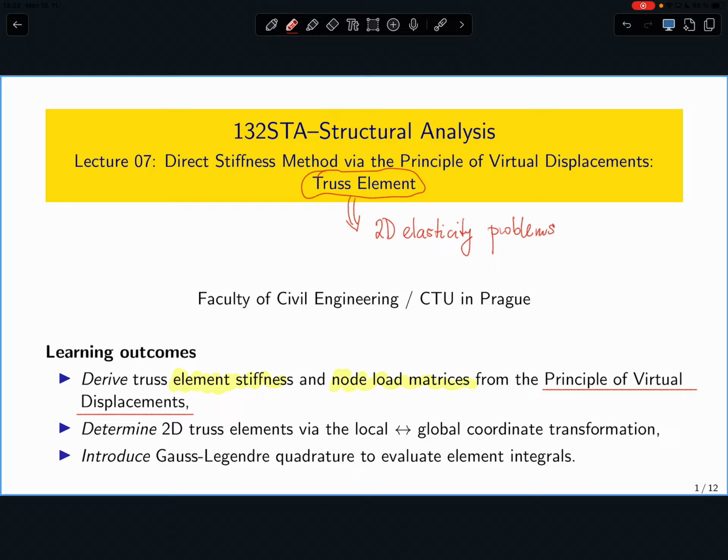And also I will get rid of the final inconvenience, which is related to the fact that I don't know whether you recall that, but Martin made it also very explicit. If you actually work with this n forces, which correspond to fixed boundary conditions, you actually need to take them and transfer them to the right-hand side and change the sign.